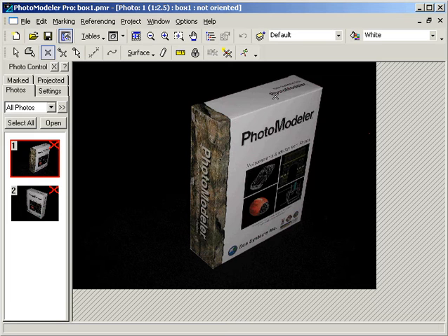On this photograph, we will model the shape of the box by marking the corners. We mark this top corner by moving the cursor over so that the dot matches the corner, and then click the mouse. A mark will then appear indicated by a small X. This marked information is what Photo Modeler needs to produce 3D results. We mark another individual point on this back corner of the box.